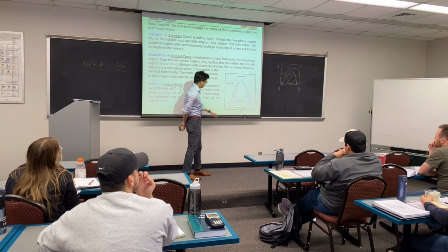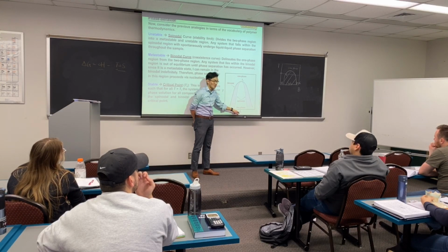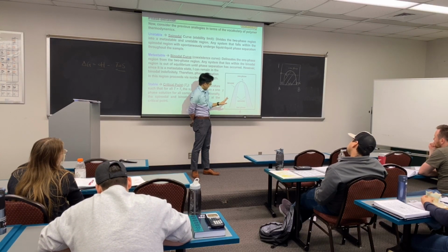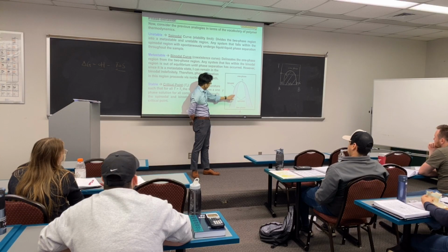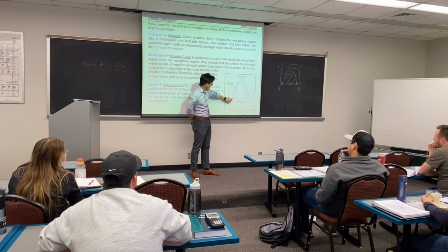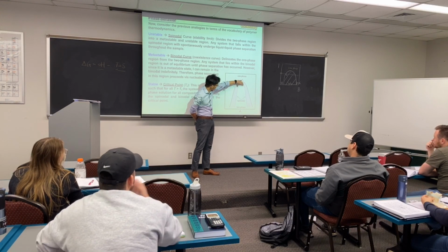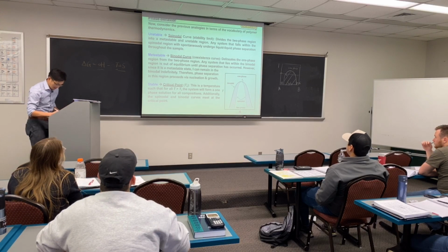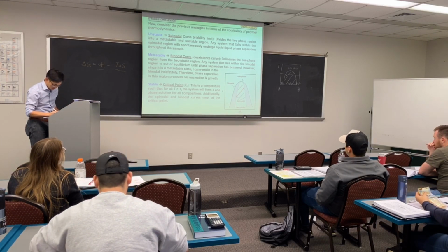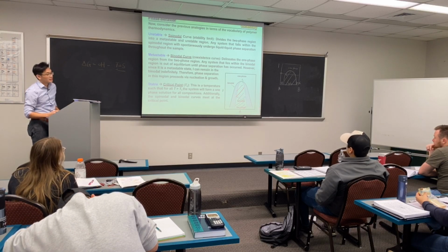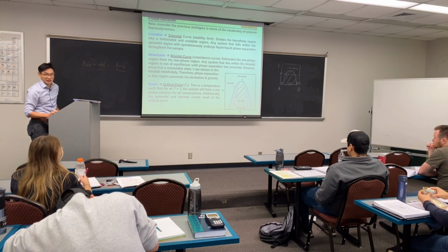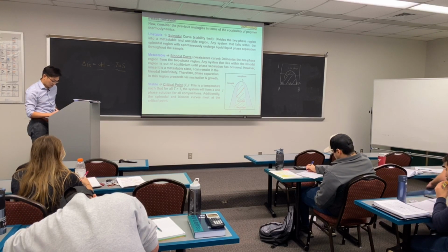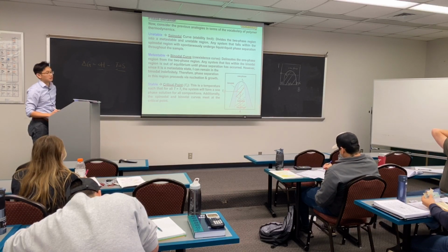This defines several different energy states. Let's say this is the phase diagram, and phi 2 is the volume fraction of the minor component, T is temperature. There are probably a lot of questions regarding what this gray area is. Let's leave it to the last. Let's first talk about this region in the center, and I can use my pen to highlight it in red. Everybody got it? This region is basically two-phase. If you mix 50-50% of your material and fall into this particular temperature, it will be two-phase.